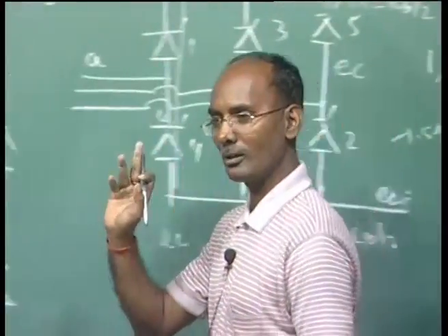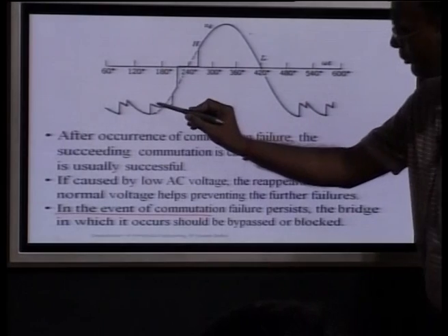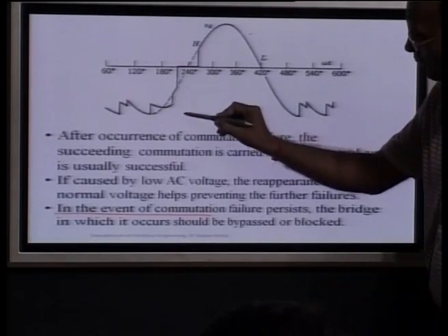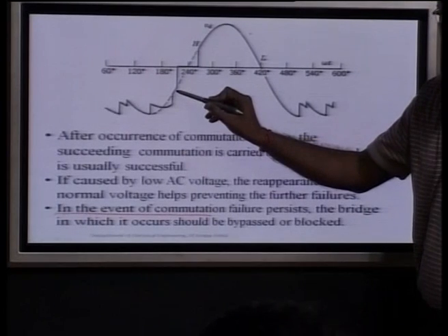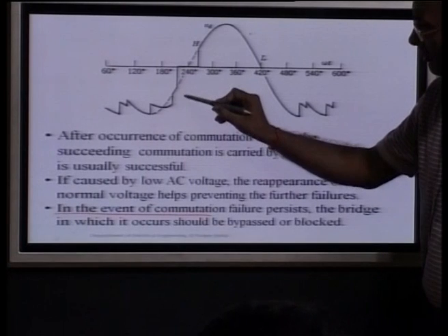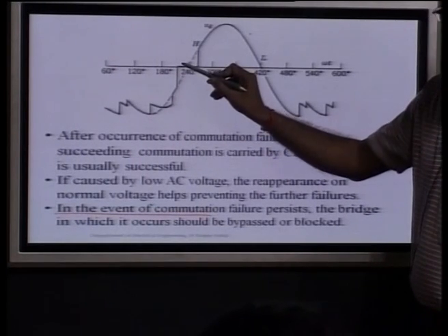Now you can see we are getting a similar pattern. Here, in this voltage, you can see this is the 3 and 1 commutation failure. Before that, 4 was fired, and the commutation was unsuccessful. Here, between this, 1 and 2 were conducting. Then here 4 was given a pulse. It was certainly a short circuit.